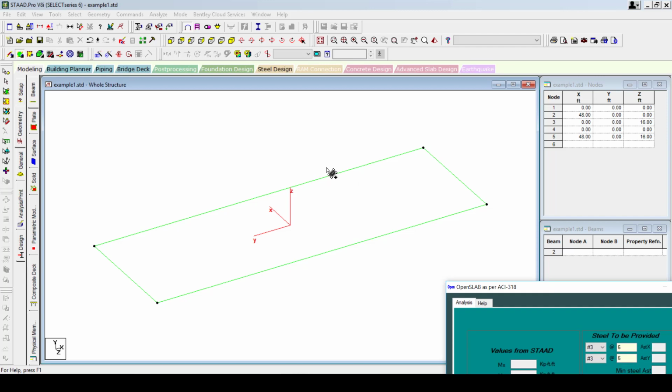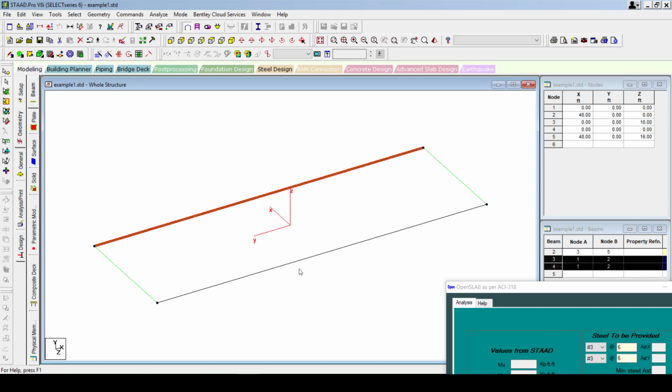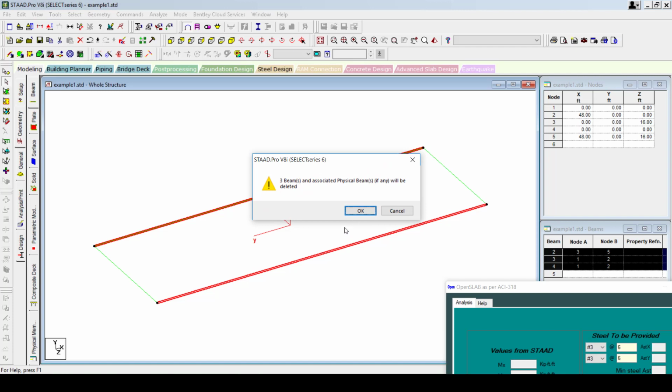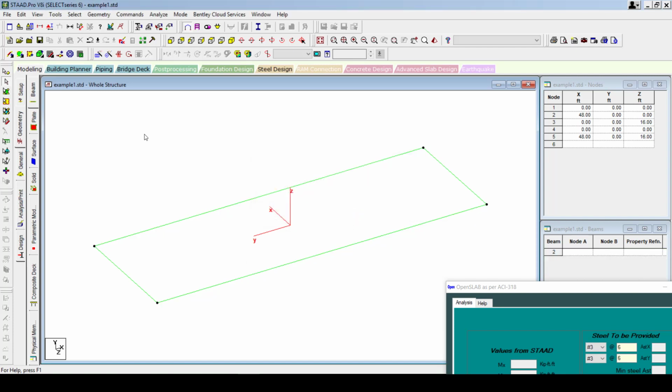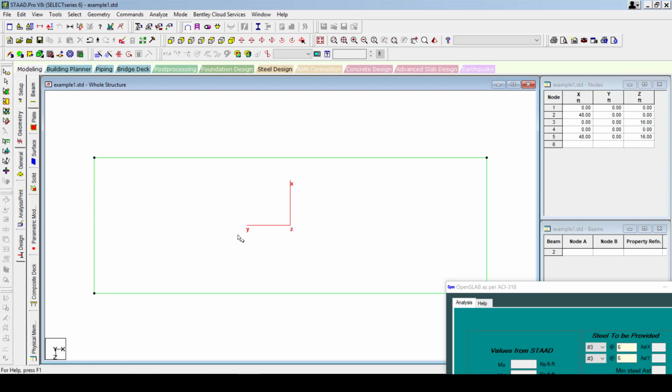Moving on, so this is my slab. This is a one-way slab. If I'm modeling a one-way slab, few of the engineers that I know like to model beams, because beams in finite element analysis pose flexibility, which is the elasticity in the beam. If we want to ignore the elasticity in the beam, just like we see in the book examples and an example like this, we simply assign this as a support. So right now I'm just going to go ahead and mesh my slab.